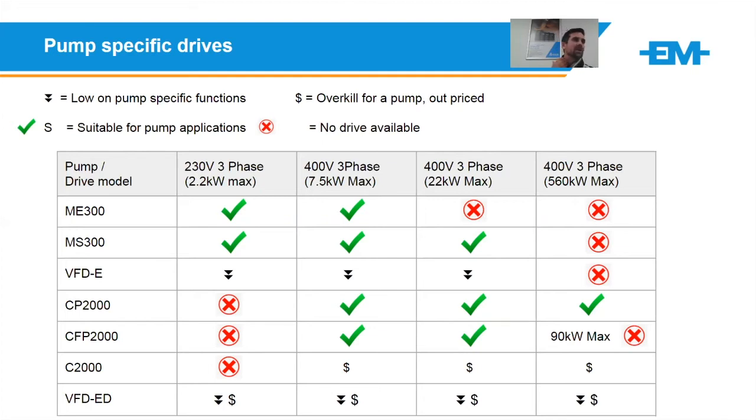A purely regen unit. So instead of your brake resistors, you would have the regen unit on the output. And when braking is done and regen happens, that regenerative unit takes that energy and switches it back into the mains so that you don't dump it and waste the energy in a form of heat, but rather reuse that energy back into the grid.